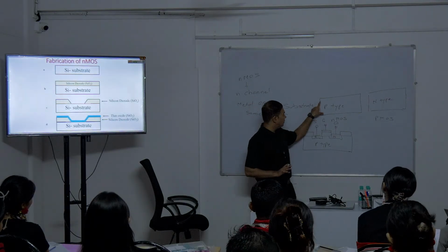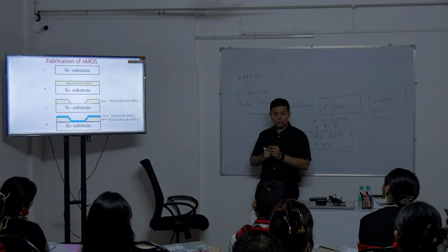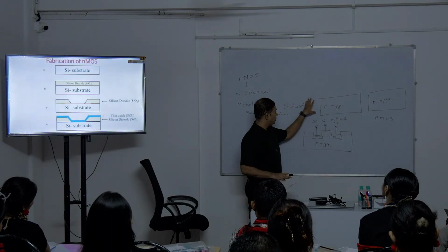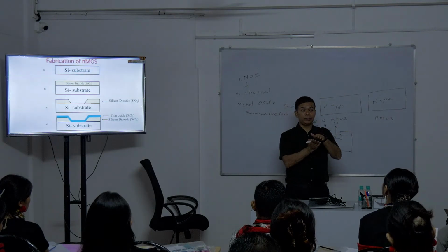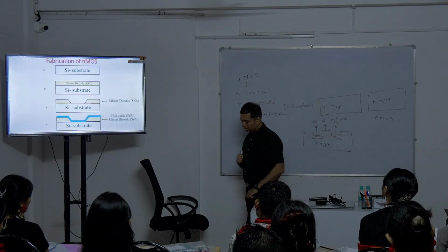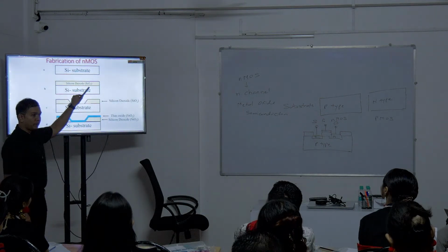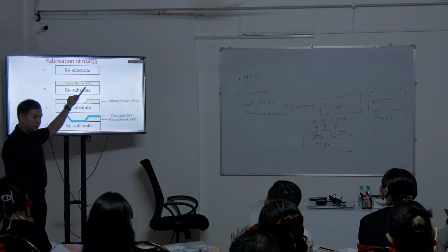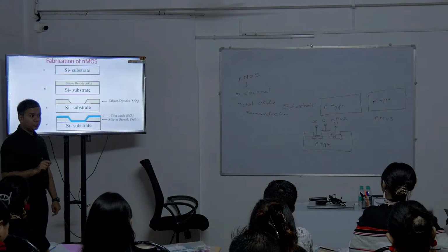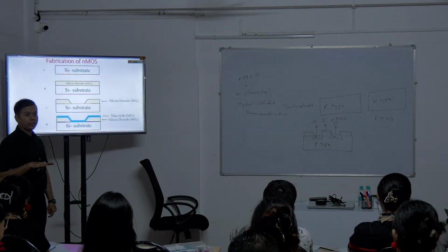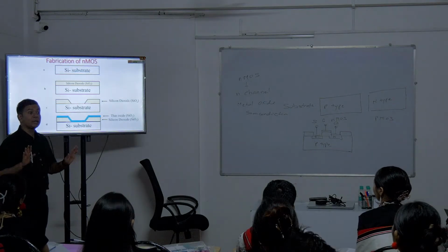So the first step is we take a substrate, right? Next, the complete surface we will pass for oxidation, because the silicon dioxide layer, can you see this SiO2? This silicon dioxide layer is nothing but an insulator. So now you should know what an insulator is. What was an insulator? It will not conduct any electricity, right?